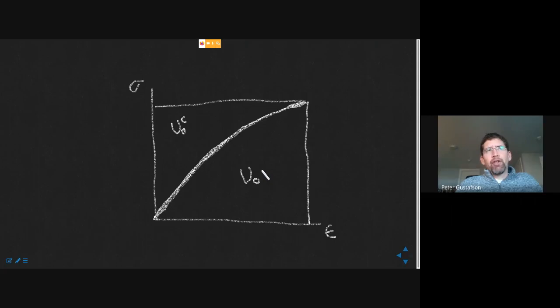But in terms of how much energy is stored to actually do work, really it's the internal strain energy that can be converted into things like kinetic energy. So if you have a nonlinear response on, say, a bow and arrow or a crossbow, the amount of energy that would be converted into kinetic energy is the area under this curve, that is the strain energy, and the complementary energy does not have a direct analog to that.